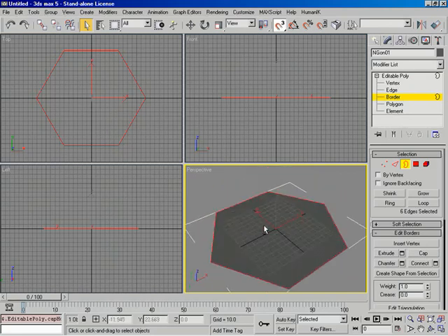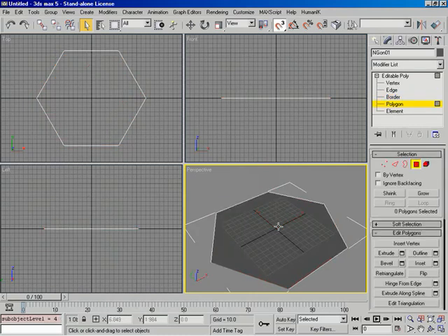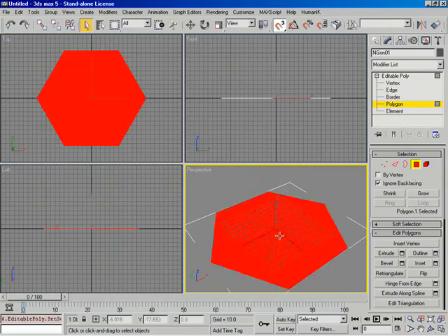Next thing I want to do is start out with getting a general shape. Let's do a little bit of an extrusion. So I'll come over here and switch into polygon mode. And just so that I don't accidentally select the back side, I will check Ignore Back Facing and then click. Just in case you don't see the polygon shaded red like it is right now, you may have to hit the F2 key. Hitting F2 will toggle between shaded off, where it's just showing me what is selected with an outline, basically all the edges outlined red, or I can hit F2 again, and then I see the actual polygon shaded like this, which works great for me.